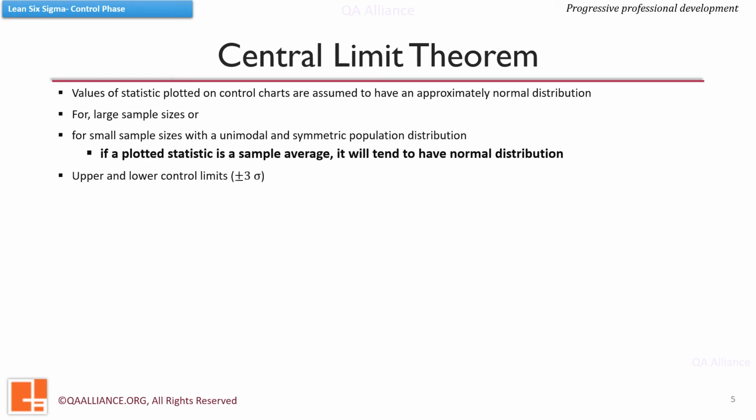The upper and lower control limits help in decision making. The limits are chosen so that the probability of the sample points falling between them is almost 1, usually 99.7% for 3 sigma limits, given the process is in statistical control.